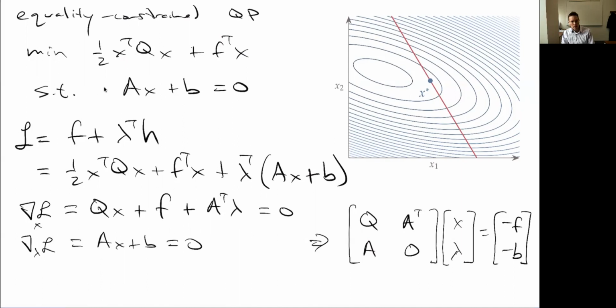Another example is if you're doing controls, you may have heard of an LQR controller, the linear quadratic regulator. The idea there is that you approximate the dynamics as linear, right? We often do that anyway in dynamics. But then you form a quadratic objective. So you would say have some quadratic sum of errors plus maybe some sum of control efforts or whatever.